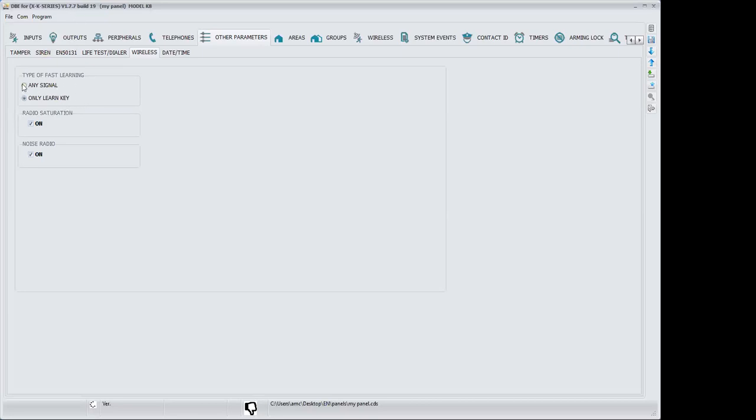If you use the default, you use the specific signal for enroll. I mean, the little red button, the little jumper. If you modify this and select this, the system will enroll with any signal, for example with the tamper signal or the alarm signal. But the problem is that if you use self-enroll, you risk that a device enters that you don't need at that moment.